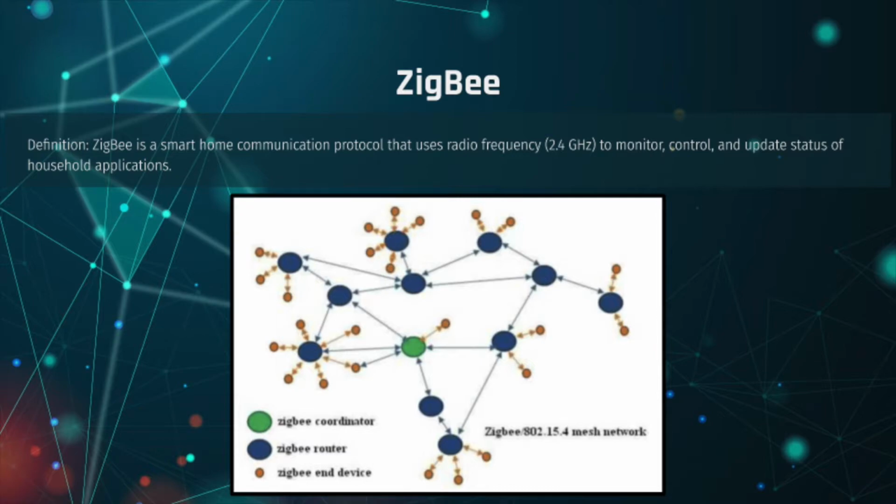At this point, the coordinator assigns a network address to itself and has completed its configuration, ready to accept network join request queries from routers and end devices to join the PAN. In addition, the coordinator sends broadcast beacon request frames on the remaining quiet channels, which is also referred to as beacon or PAN scan, to receive the PAN ID of routers and end devices present nearby.